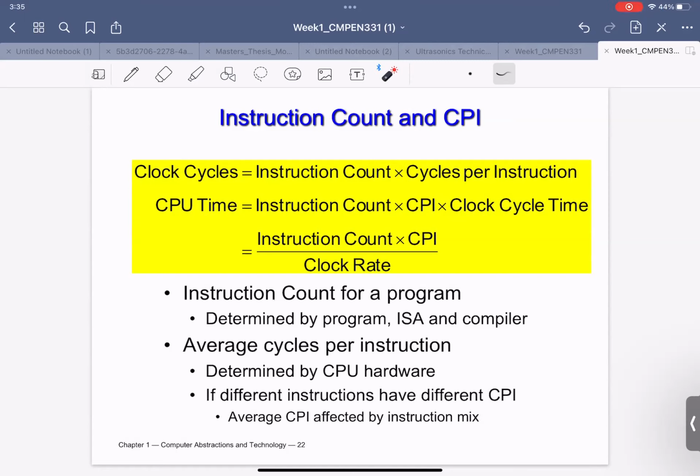And I'm asking you, what is the total number of clock cycles? So 2 multiplied by 7 will be equal to 14, because 2 per line, and we have 7 of these. So instead of 3 multiplied by T in that example, it will be 14 multiplied by T. So now I know how I can calculate the clock cycles.